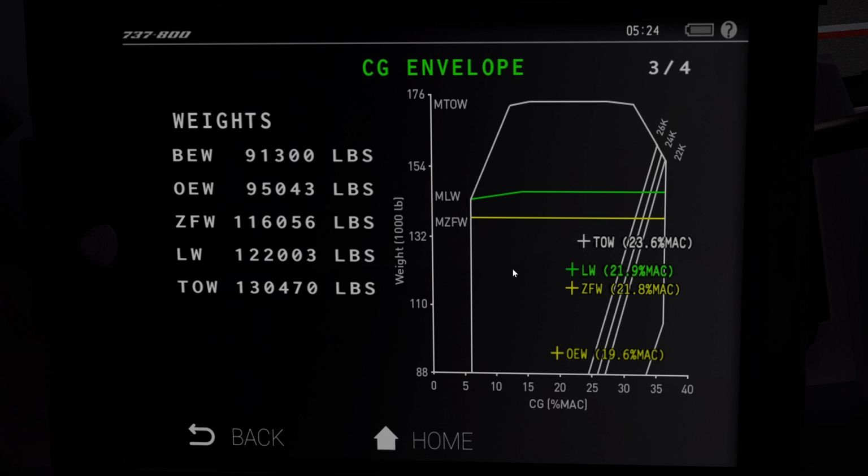At this point, the nose of the plane is getting heavier and heavier. If we are going forward, it will be less maneuverable because we need more force. I tried these values below 20, like here it was 19 and here it was around 16-17%, and I noticed that there are some instabilities when the plane is on the glide slope. So Autoland sometimes succeeds, sometimes not. Most of the time Autoland will not work. Therefore, I have decided to move these center of gravity points a bit back. There are two important weights here in this list: the landing weight and the takeoff weight.